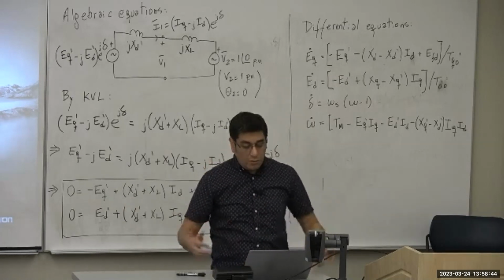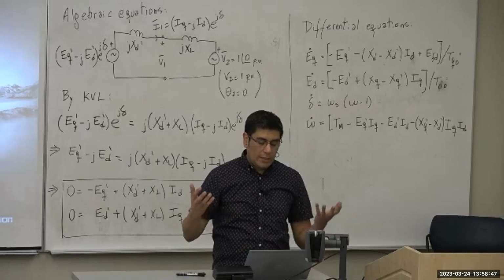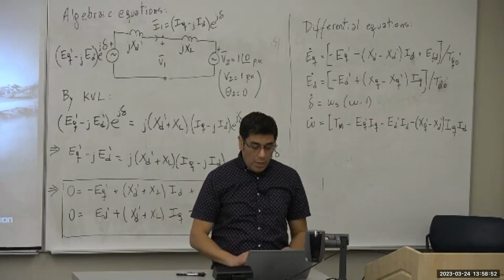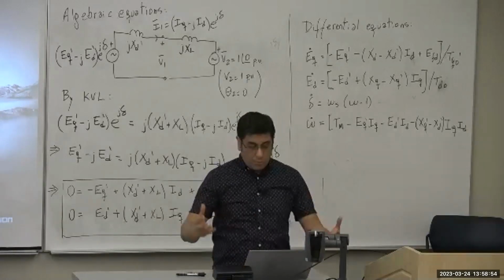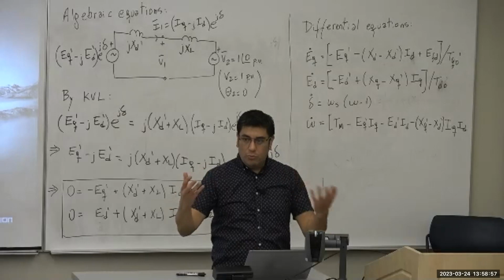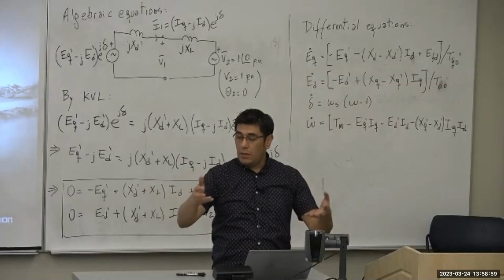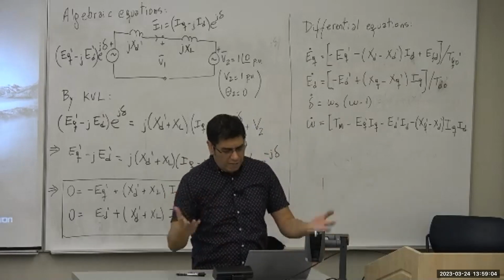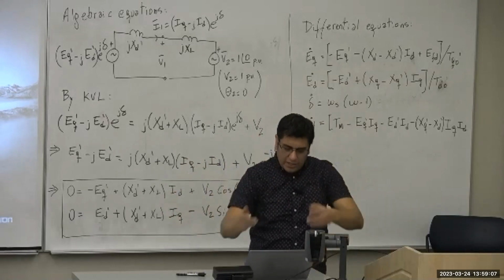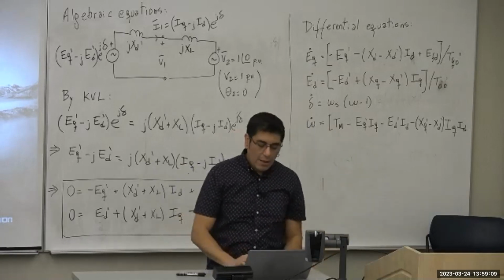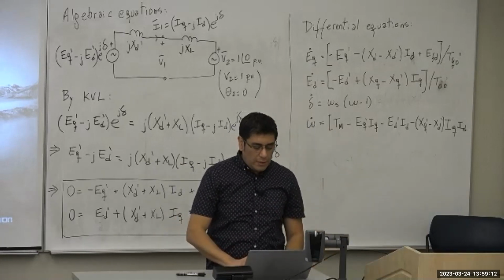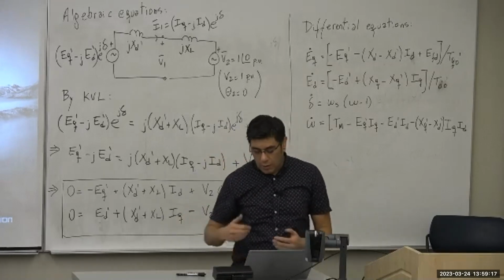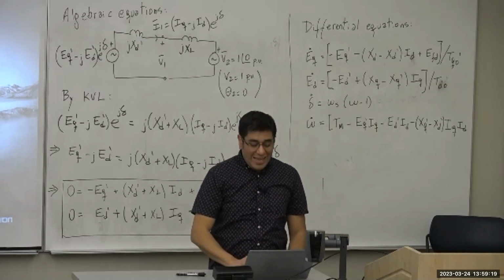As David mentioned very well last class, we don't need a formal power flow set of equations because the system is so simple, and we can use the expression we know for the power flow between 2 points that uses the voltage magnitude and sine of the angle, because the system doesn't have losses. And all of this needs to be divided by the equivalent reactance. So we discussed this expression, and there is the solution for theta 1, the angle at the terminal of the generator.